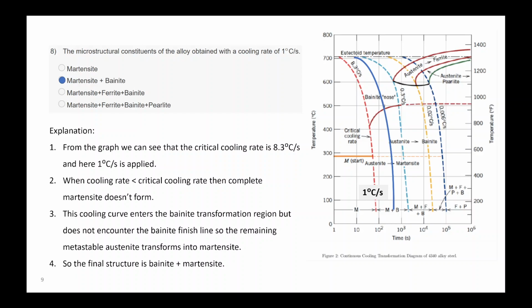Okay, ma'am. But actually, in that slide, it was given like grain boundary is not actually the reason for the hardness enhancement in the metal. Actually, the size of the grains will be affecting the hardness, isn't it? What is given is like a grain boundary also acts as a source and sink of dislocation, but that's not the reason for hardness enhancement in metals.